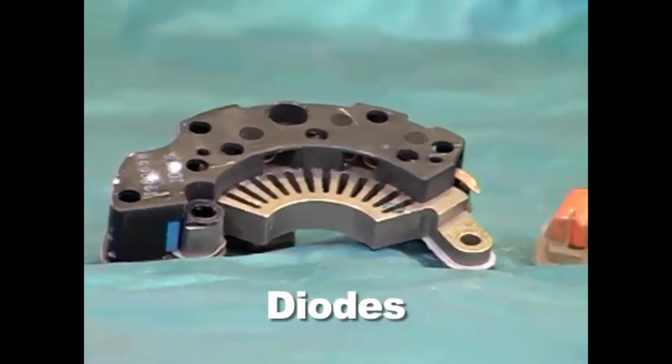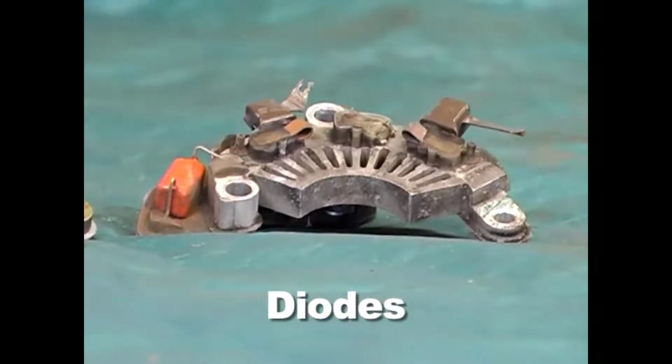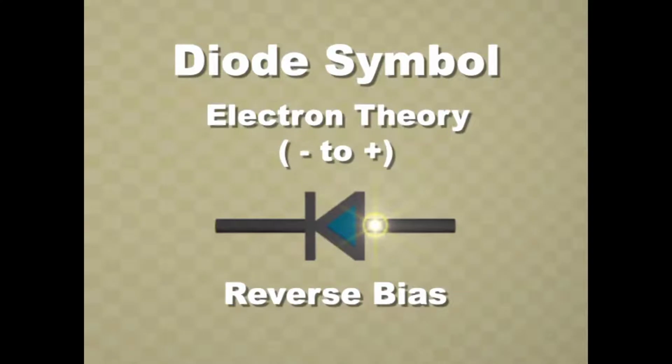Rectification uses diodes to convert alternating current into direct current. A diode is simply a one-way electrical check valve. With electron theory, a diode will conduct current when forward biased. Note how the current or electron flow is blocked when it tries to flow through the diode reverse biased.